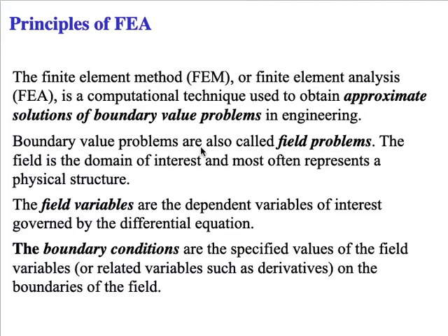The boundary value problems are also called field problems. The field is the domain of interest and most often represents a physical structure. The field variables are the dependent variables of interest governed by a differential equation. The boundary conditions are the specified values of a field variable, or a related variable such as derivatives, on the boundary of the field.